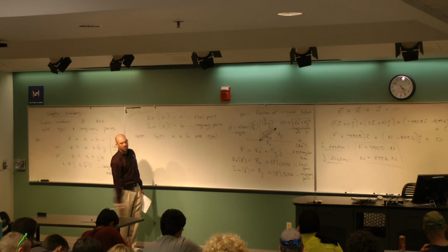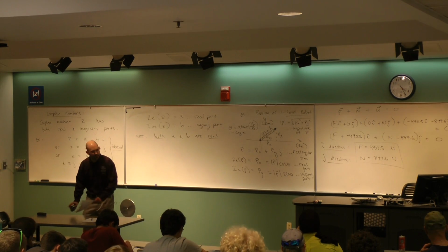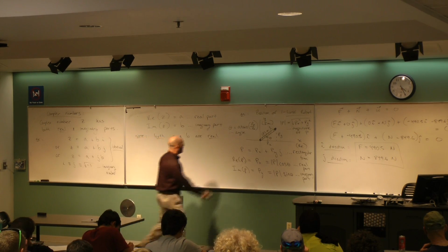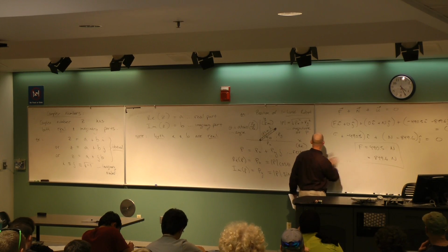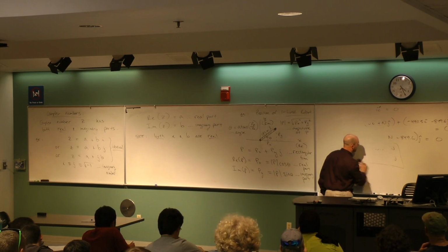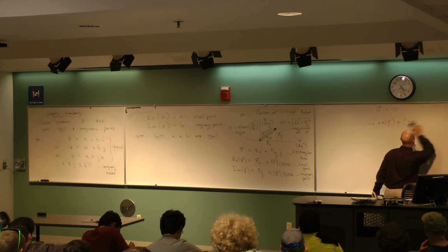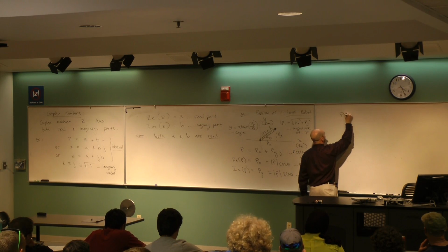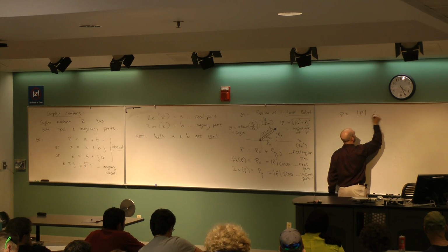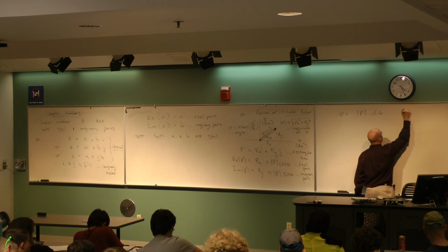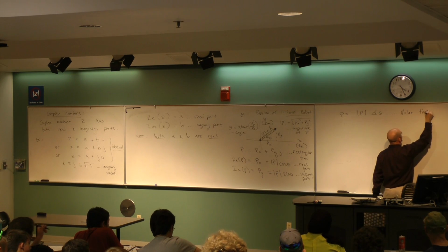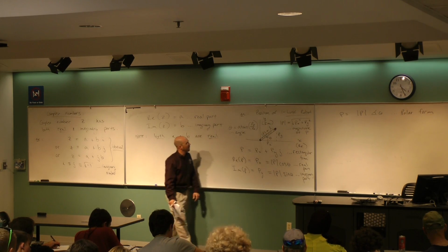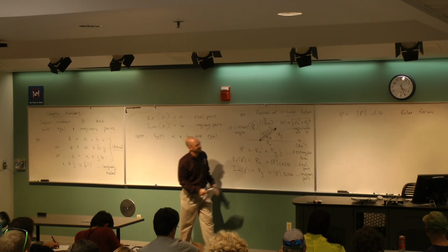So geez, this just looks like a review of trig and vectors again. I got a hypotenuse, I got x and y components, I got an angle, I got a magnitude. Well, P equals Px plus Py times j. That is the rectangular form. I can also write this thing just like a vector, not as components, but as magnitude and direction: P is the magnitude P at an angle theta. This is the polar form of a complex number. How do I get the magnitude P? Right here, Pythagorean theorem. How do I get the theta? Right there, atan2.